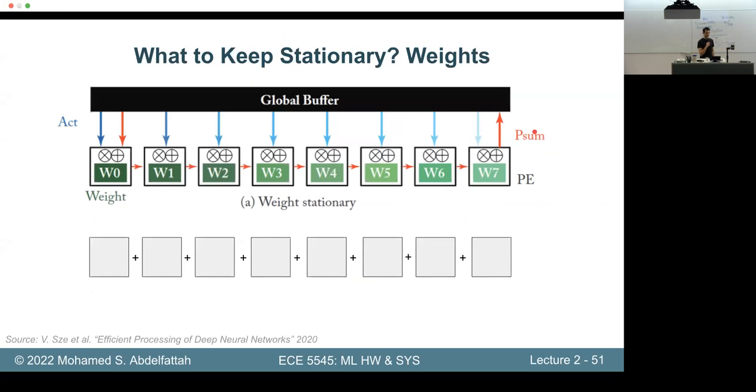And so this idea of reuse sprouted this term of stationary, to keep stationary in your application. So you have your activations, you have your weights, and then you have the results, so the new activations. So inputs, weights, and results or output. And usually people design their compute hardware such that you have one of those things not moving, basically. So they would have them stationary in your PEs. They stay there until I don't need them anymore.